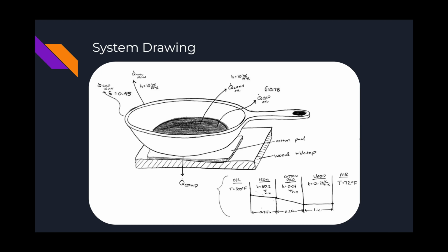however, not nearly as much heat as the radiation from the oil in the pan, which is our third form of heat transfer. Radiation, transferring heat through electromagnetic waves, ended up being the number one source of heat loss from both the pan and the oil, which goes to show how important it is to factor into your calculations.